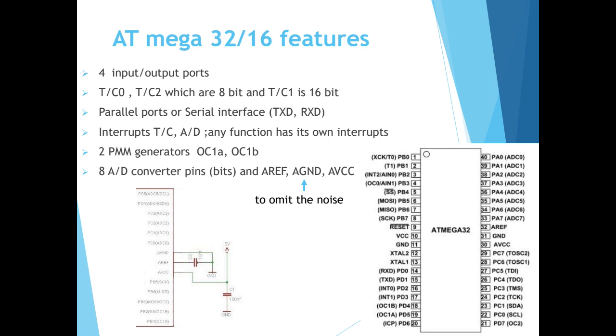Another feature is the serial interface, which is related to pin 14 and pin 15 of the D port. As you see, RXD and TXD are related to the serial interface. Interrupts: timer counter or analog to digital converter, any function has its own interrupts.